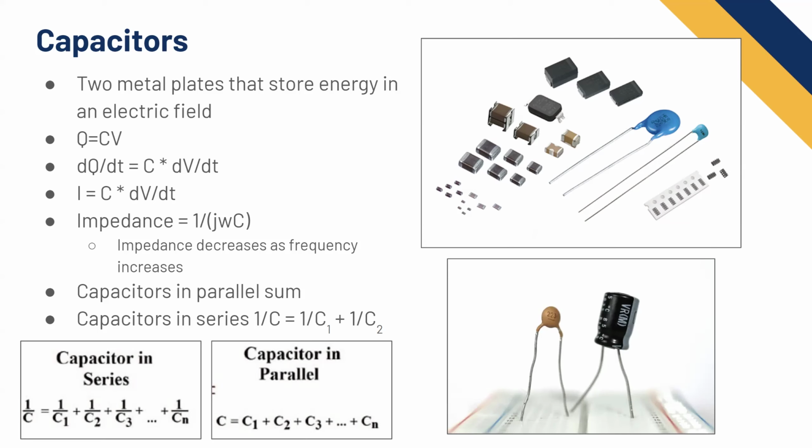And then this photo is just some various capacitors you can see. The ones on the bottom left are MLCCs, which is multi-layer ceramic capacitors. It's basically modern chip capacitors. It's a bunch of layers of metal with dielectric between them, and they print it similar-ish to how circuit boards are printed. It's basically a lot of layers. And then it's a ceramic dielectric. Then you have the ones on the top that are in the black casing. Those are usually more specialized capacitors. They're usually polarized, like tantalum capacitors. If you look those up, they usually come in those packages.